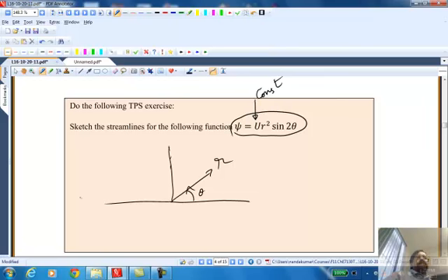When you're drawing a curve, what do you need? You need a set of coordinate points. So if I give you a series of coordinate points, r and theta values, on which psi is a constant, you can just connect all those points, and that's your curve, right? So you need to generate such a set of points, a table of r, theta points on which psi is a constant.